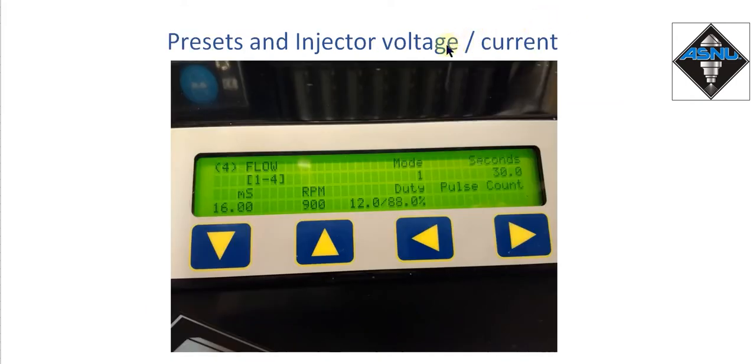The standard ASNU machine always drives the injectors at 13.8 volts and a fixed current, and it has a limited number of presets for pulse width, engine speed, duty cycle, and flow test time. Combined with the optional variable voltage power supply, the remote control software allows you to set your own injector voltage and current and an infinite range of pulse widths, engine RPMs, duty cycles, and flow test times.